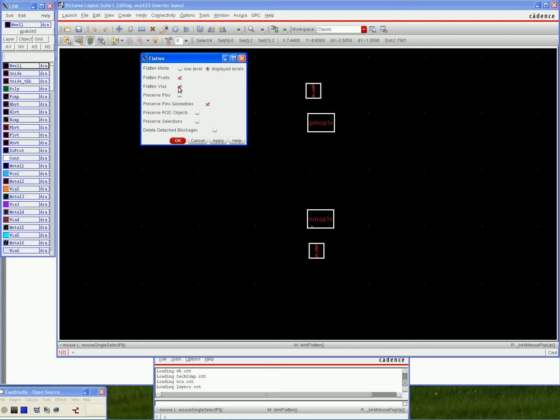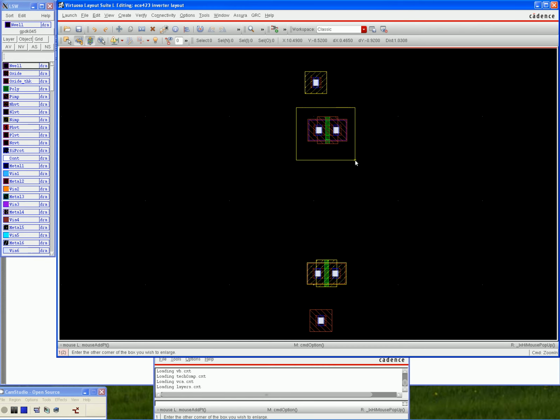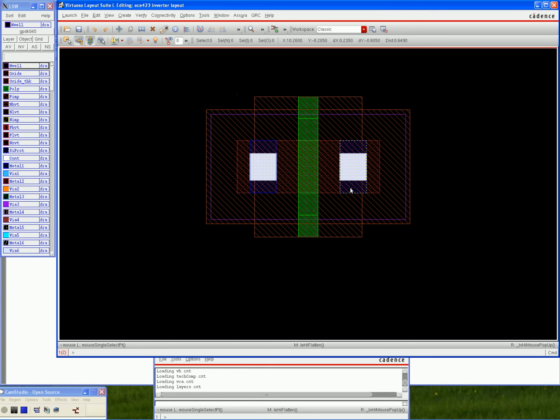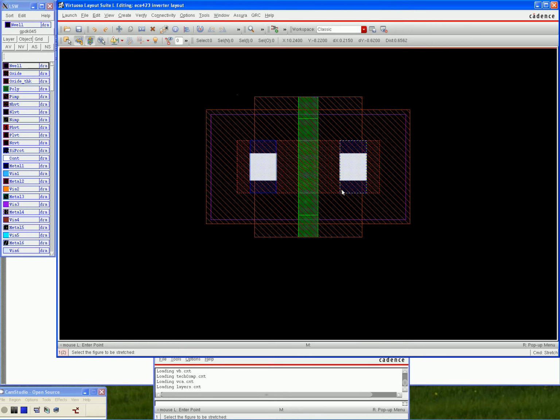And now we need to create two vias. We create via, and for the first one, we will choose the via definition of M1 P implant. And hide, and we'll place it directly below our NMOS 1V. Next we will create the second via. It is of type M1 N implant. And this will go directly above our PMOS 1V.